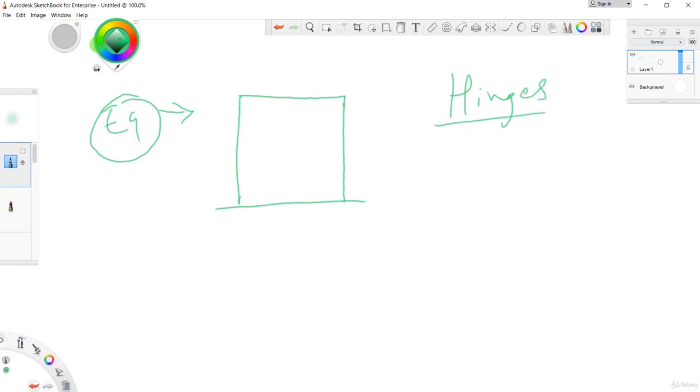Okay, so what are hinges? Hinges are those points on a structure where cracking or yielding is expected to occur under the earthquake loading or the cyclic loading. These points are normally at a beam-column junction. So right over here, and here, and here. If we've got further columns, then we've got 4 columns here, and beams here and here also, right? These hinges we have to assign to beams and columns in SAP 2000. It helps to study the plastic rotation of the building.